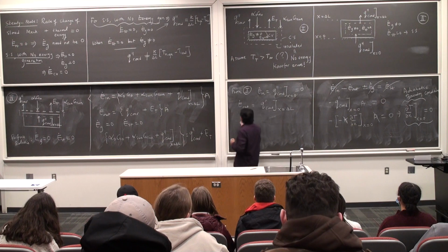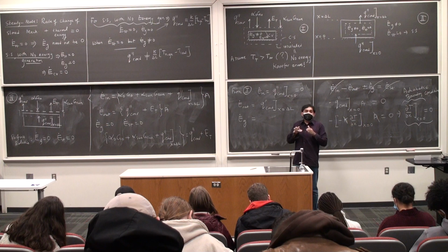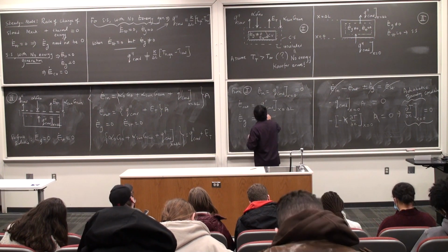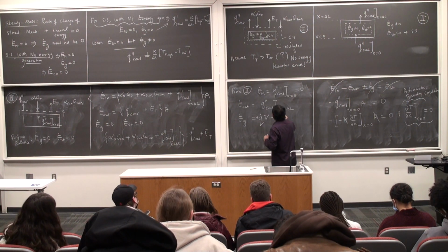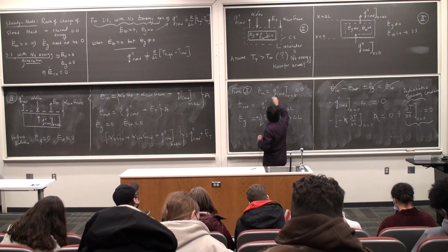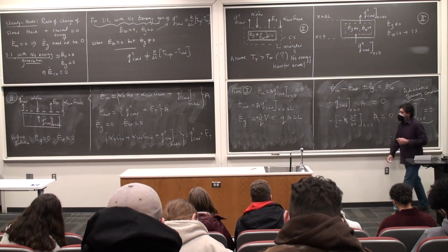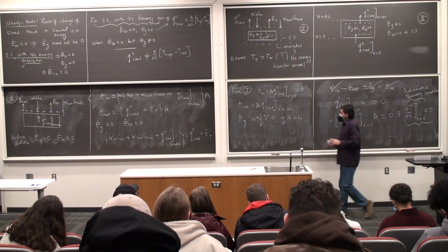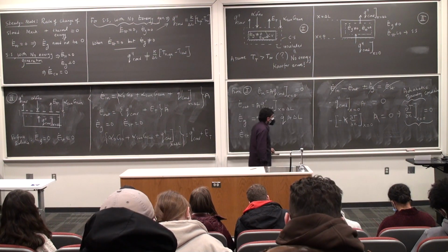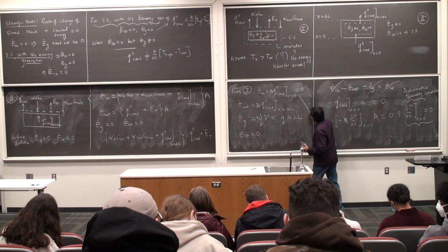Then I write E dot G. Be careful, this is not 0 because now I'm looking at a volumetric phenomenon based upon the way I've drawn the control surface in there. This is plus q dot times V, or q dot times area times delta L, and I have to apologize, I have to write the areas here, sorry. Area times all of that. Flux times the area is the total heat transfer, right? E dot stored is 0. And this was from